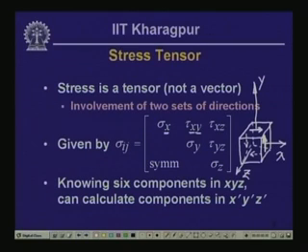So, the first subscript which is going to go with this shear stress is going to be x, and since this shear stress is occurring on a plane for which the outward normal is aligned with the positive y direction, the second subscript is going to be y. So, these shear stresses are going to be called tau xy. Similarly, you could have tau xz and tau yz when you consider the other planes.